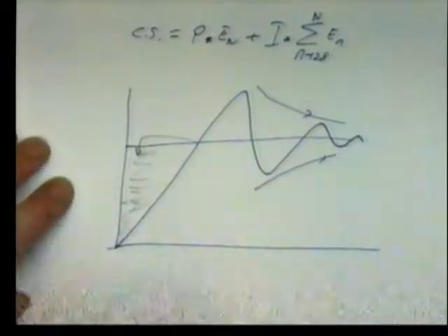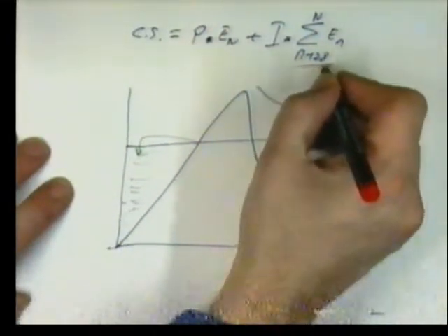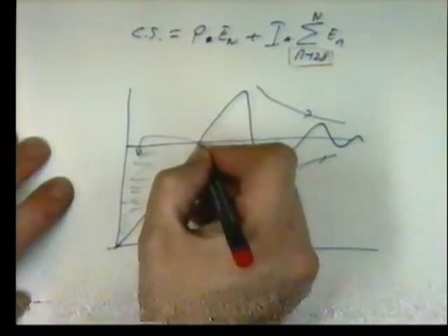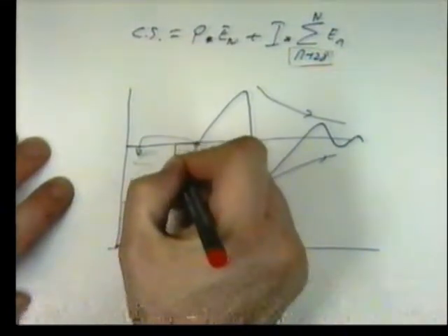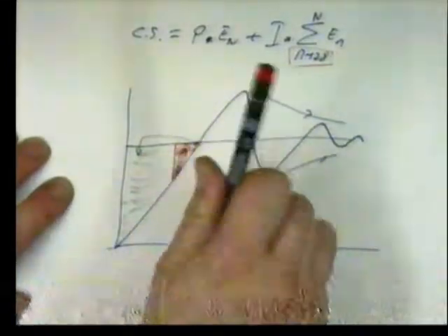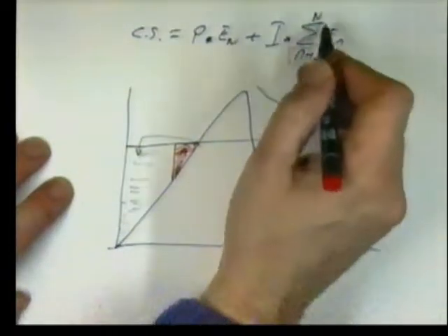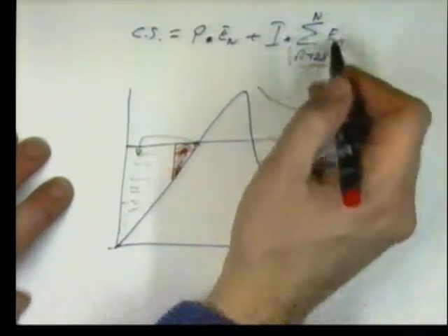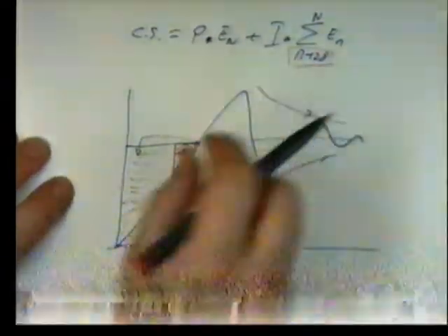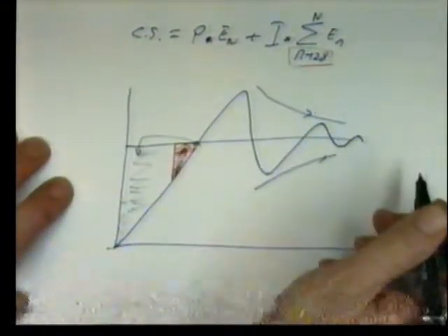Now, one cure for that is to use this summation approach, whereby instead of integrating from 0, you only integrate over the last 128 samples. So at that point there, all we integrate is the last 128 samples, rather than everything from history. And that's a moving window moving with us. By using an array in a computer, this is a computing technique as opposed to a traditional control technique. By using an array, we have a moving window on the errors, and so we have more stability.